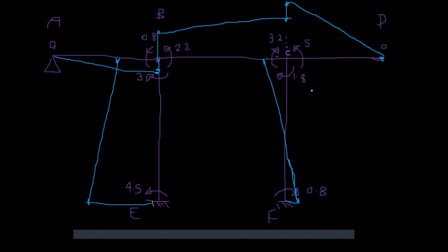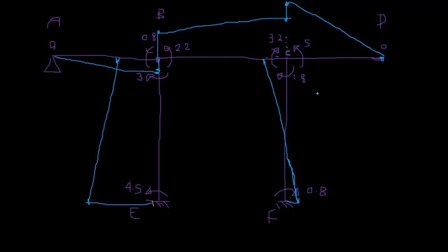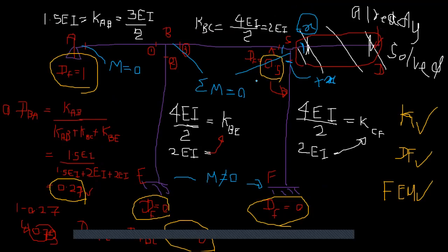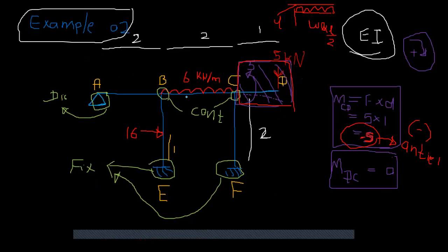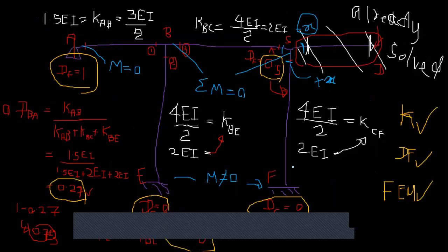So this is your support bending moment diagram, right? So now I need to find what. Usually supports are considered to be hogging, right? Not always that way, but usually support bending moments are hogging, but can be different as well. So you need to just consider the bending moment due to the simply supported loading, right? So it's only BC and BE.